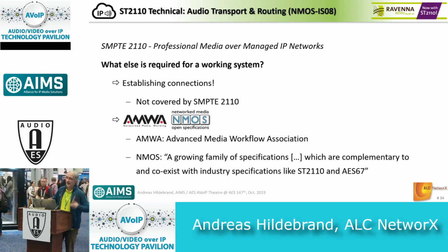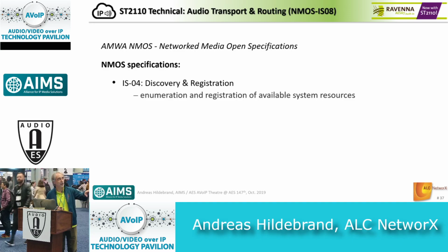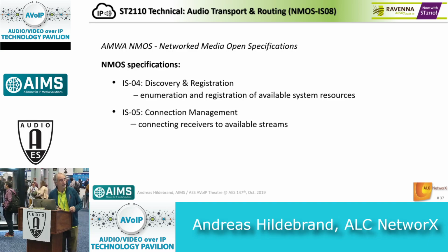So it's enhancing the functionality of 2110 and AES67. The applicable NMOS specifications are IS-04, which covers discovery and registration so that systems know what is actually available on the network, what devices are available, what streams are currently configured, what receiving endpoints are available. That's all about discovery and registration.